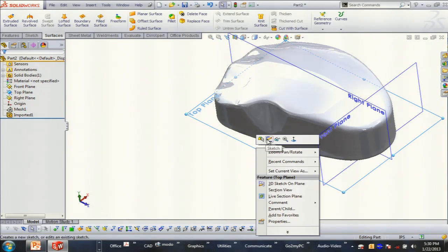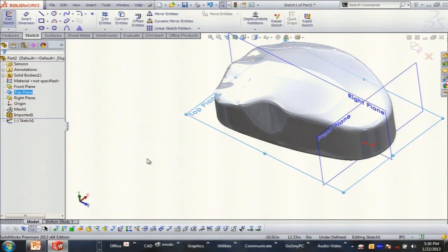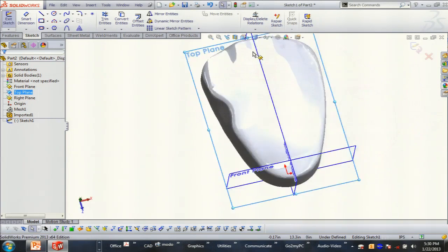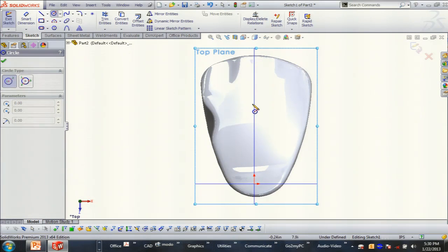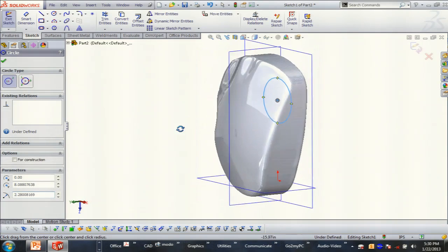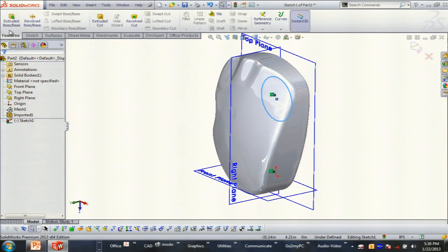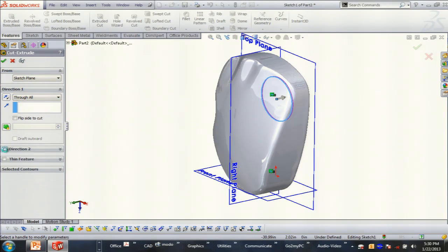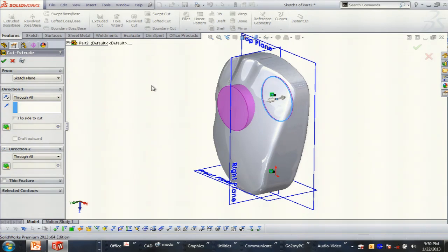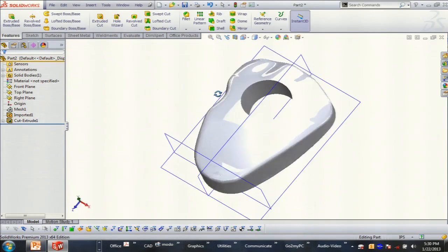So the automatic surfacing tool doesn't really work for these types of objects. It's really good for highly detailed stuff, but it does make it a solid model. If I want to punch a hole through this just to prove to you that this is solid and you don't believe me, let's go ahead and punch a hole through it. I'll go both directions. And there you got it.